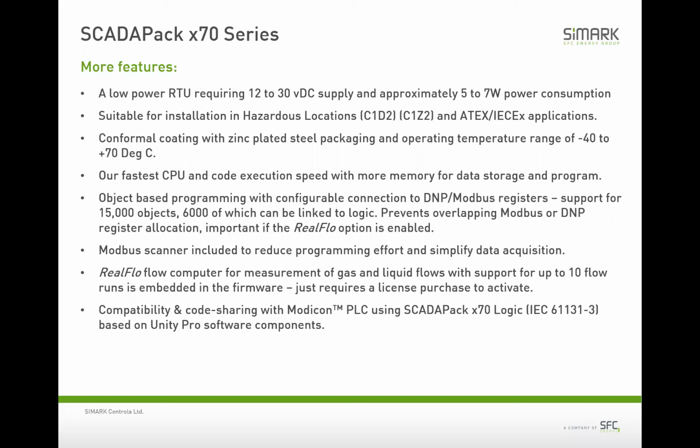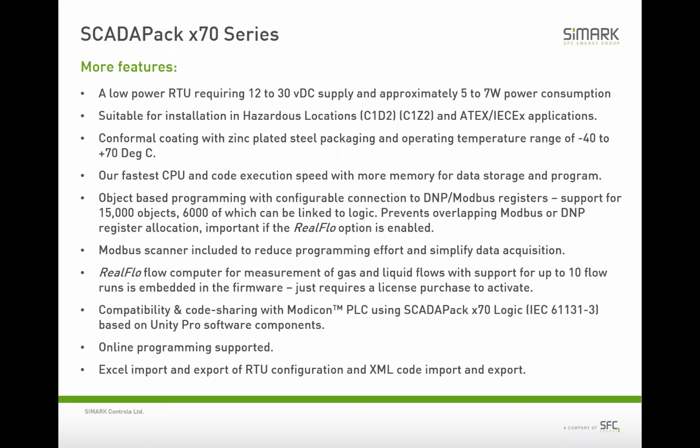The logic editor has come from the Modicon PLC programming world. It's the Unity Pro software components that are being used to allow code creation on the SCADAPack, which is giving us the IEC languages, the ability to create your own function blocks, and the ability to work with the object-based environment. And fortunately, we're still retaining the online programming support. And we've also added a lot of support for Excel and XML, import and export of code and RTU configuration to improve the ability to do bulk configuration.